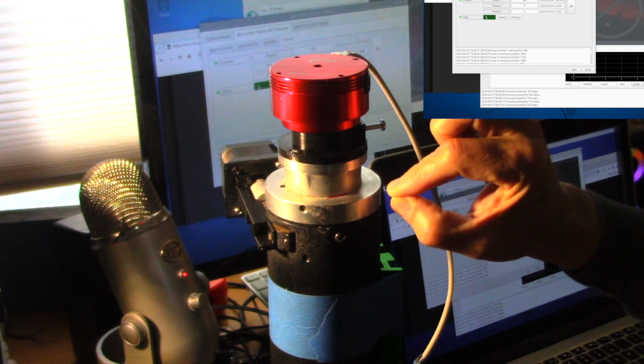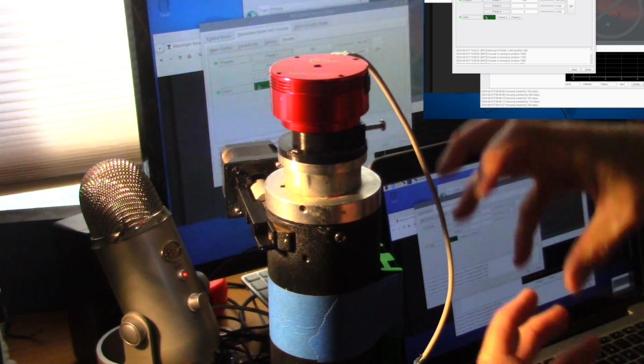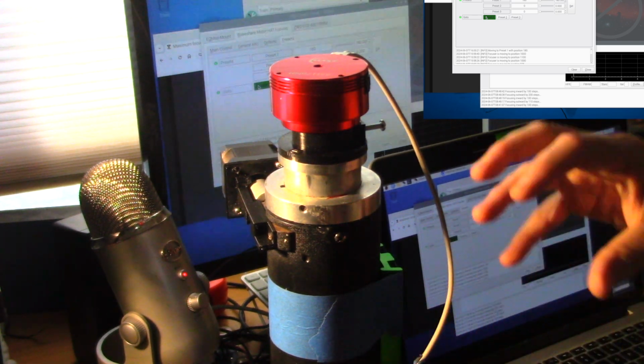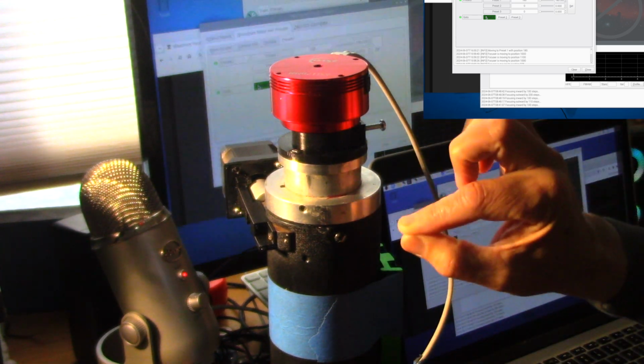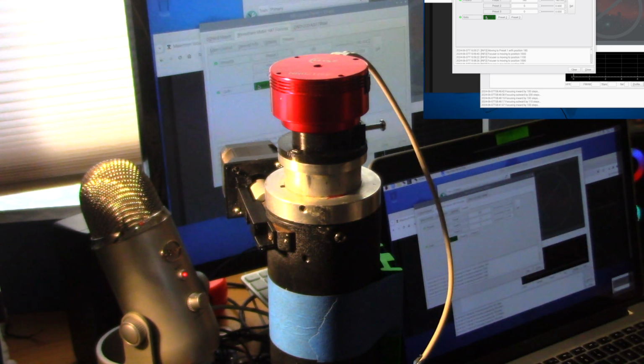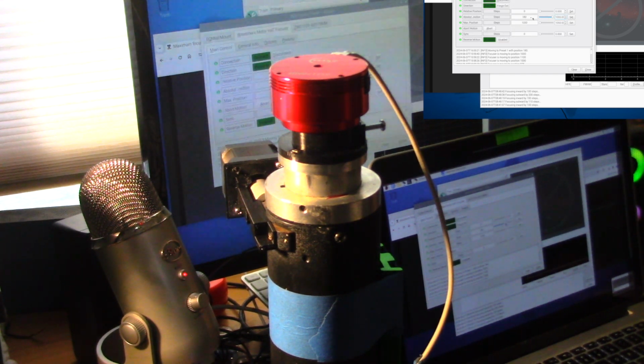And you can see that it missed it just a little bit because I've done this 2 or 3 times in preparation for this video. And so it moved just a little bit. And so what we want to do is maybe fine tune where that is. Go back into motor control and let's go to an absolute position of say 185 and see if we can get a little bit closer to where that mark is. Okay.